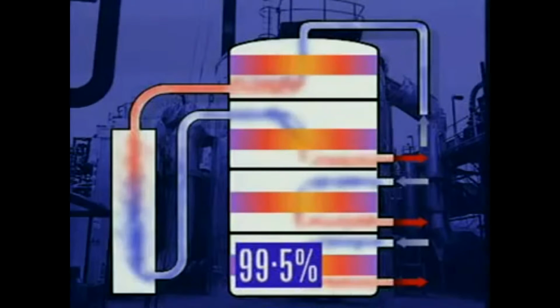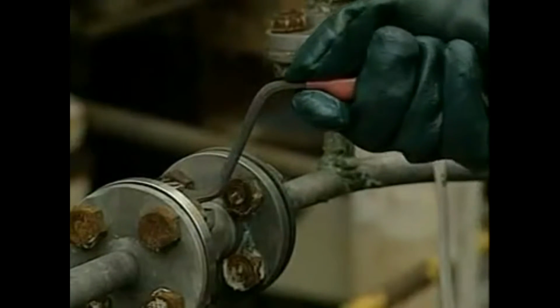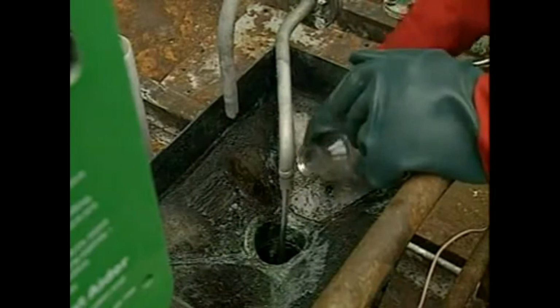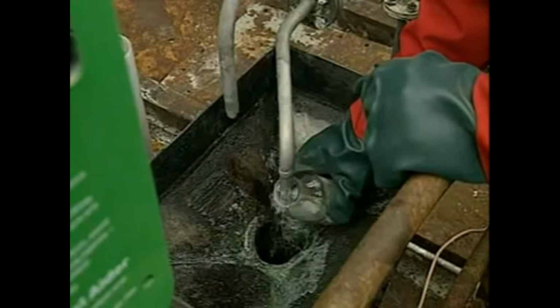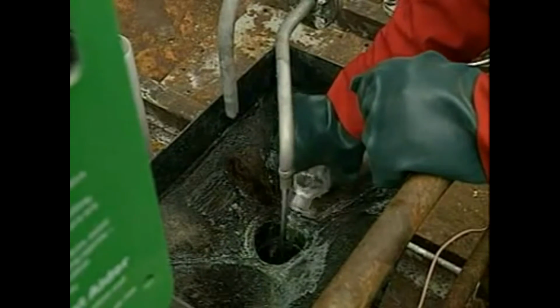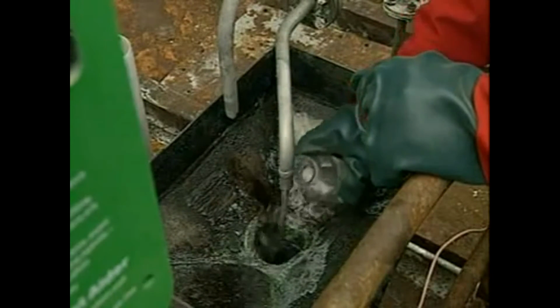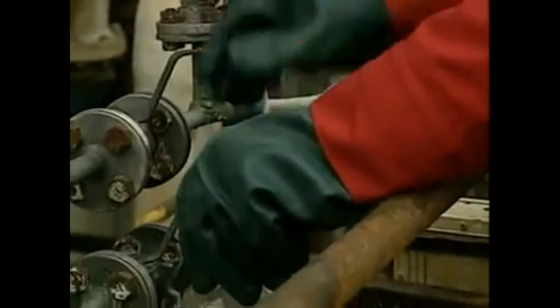The 99% concentrated acid is diluted with water to about 98%, for example, and this increases the volume of the acid. This extra 1% or so is the volume of the acid that has been made. The acid concentration is checked by sampling.